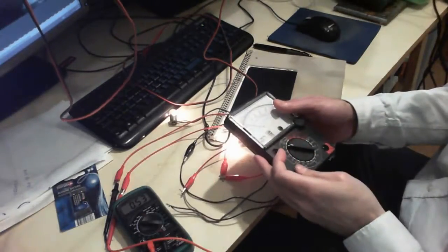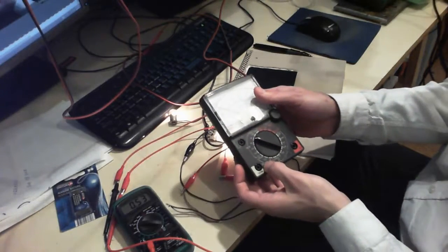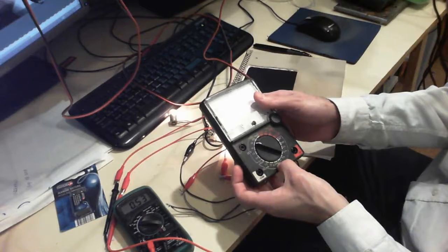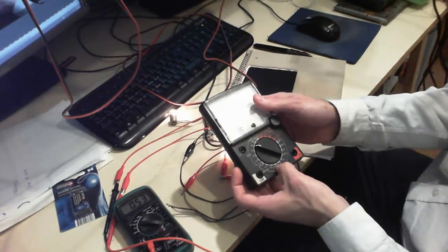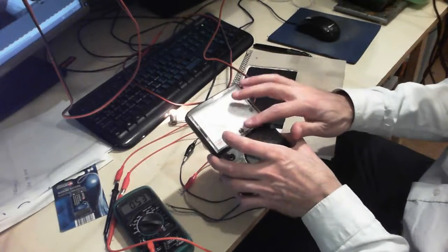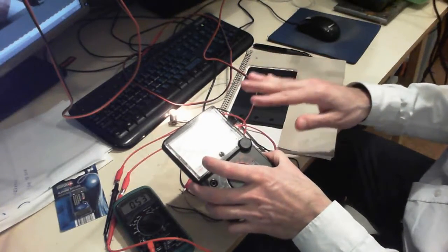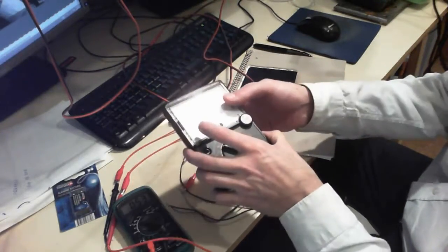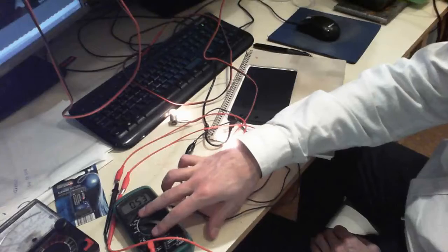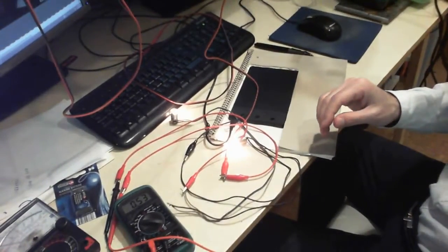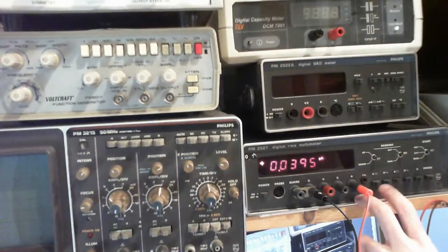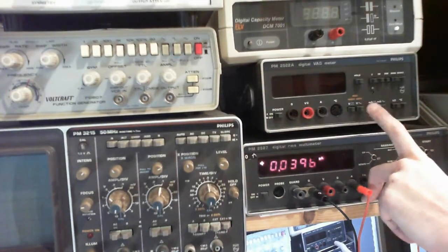And we can do that here as well. I guess we could, I don't know. Here you have, for example, DC milliamp. It goes all the way from 50 microamps up to 0.25 amps, meaning 250 milliamps. But this is not going to be enough, for example, for this circuit. For very sensitive work and very low consuming electronic circuits, you can use this. Otherwise you will have to have a good amp meter. So this amp meter can measure up to 10 amps DC. This amp meter over here can measure all the way up to, I guess, 2 amps, and this also, I guess, 2 or 1 amp, something like that.